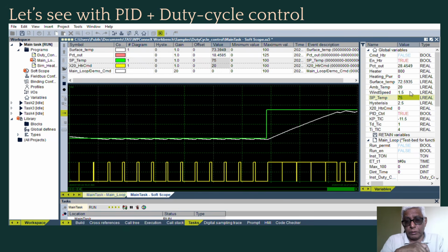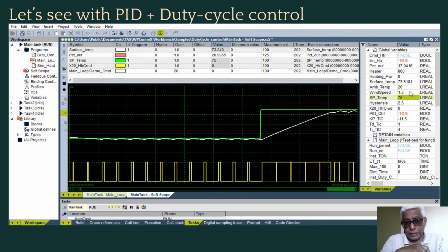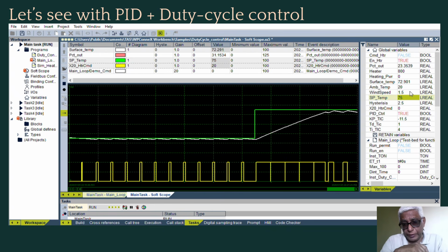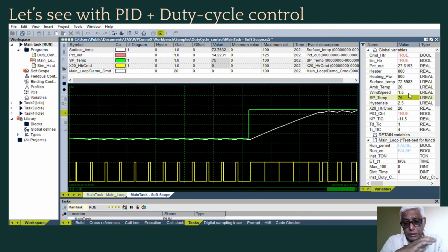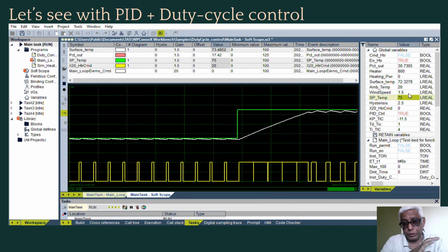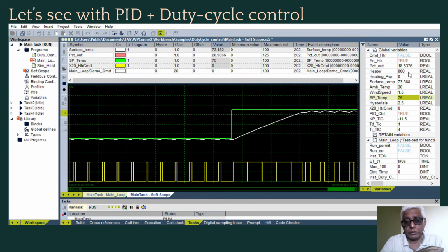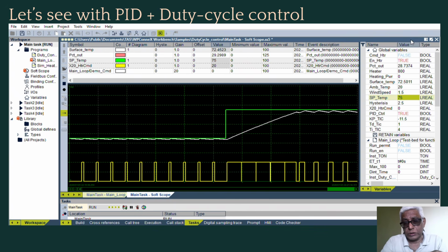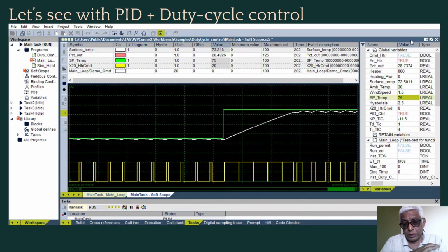Now all this is simulation and it doesn't look to be working perfectly. But let me assure you that in larger time constants and with a properly tuned PID loop, this will work very well, because there is all the time available to adjust itself. When heating and all, several minutes cycle time is par for the course.